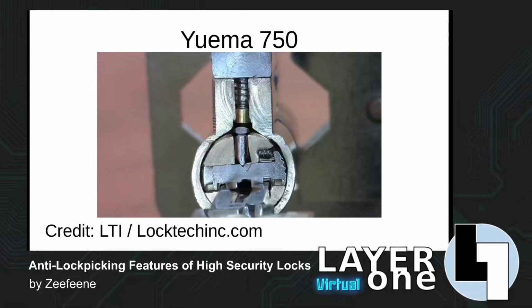So the Uema 750 is an interesting mechanism. This is a Chinese-made Eurocylinder as well. This one is a little bit more fancy. It is again a reverse sidebar mechanism, but this one actually uses a reverse sidebar in two parts. And the benefit of that is in this particular configuration, if you attempt to tension the lock, it will just spin round and round and round.